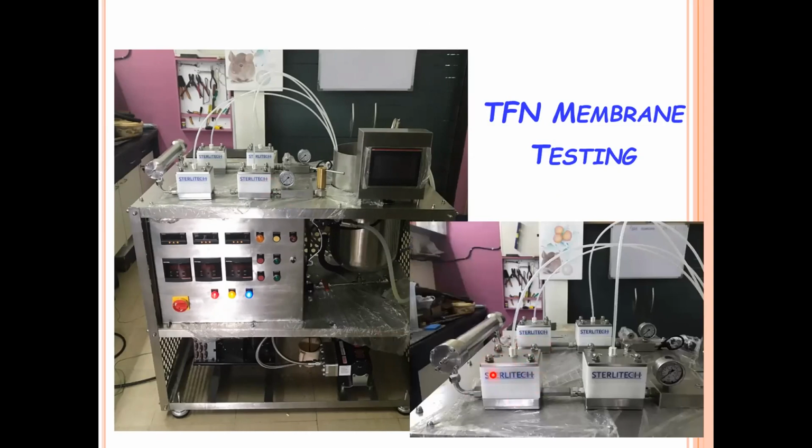So you prepare a membrane, and around 42 square centimeters of the membrane area is placed up here, and you can conduct the studies. If you prepare, say, ZnO and the combination of GO and ZnO, then you can use all 4 skids. For different materials, you can dedicate each one of them, and in parallel you can test the performance of the membrane module. This is especially for the hollow fiber portion of this membrane module. This experimental setup is in our laboratory, and we can freely use it for all our hollow fiber as well as flat sheet membrane analysis.